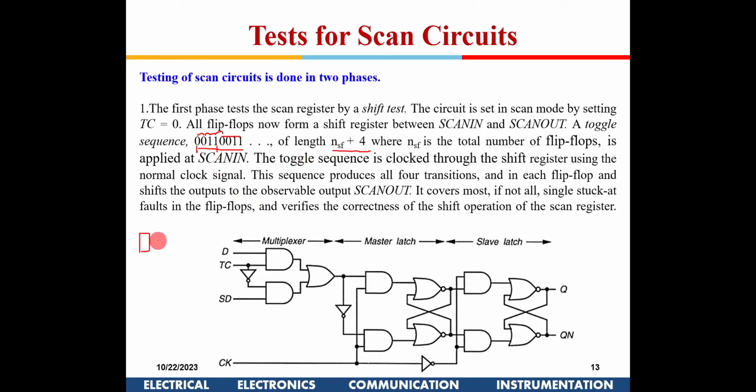Now let's take two flip-flops and see whether what I am saying holds. Suppose there are just two flip-flops, and I am giving an input. Initially, both were x. In the first clock, I put a 0 here, so this is x, and I am reading the output out here. In the next clock I again give 0 here, so this 0 will come here.